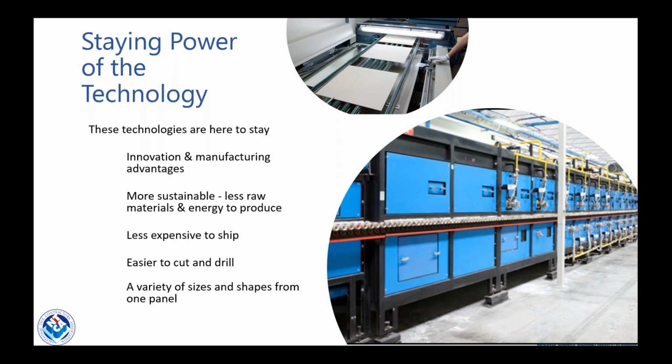Pretty much just score it with a glass cutter and snap it. And again, there's the large variety of sizes and shapes that can be cut out of one single panel. So some huge advantages in this. And I really believe that's why this is here to stay. And the innovation that we're starting to see, again, like thick tiles now, really interesting.